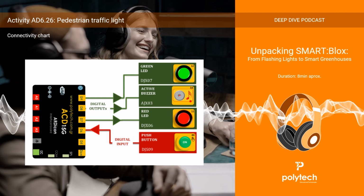The goal here is understanding digital read, checking the button state, and if-then logic, plus the digital write and delay we just saw. So if the button DJS09 on port D6 is on, then the green LED D9 and buzzer D8 turn on, the red LED D7 turns off, and it waits for 5 seconds. And if it's not pressed, that's the else part. Red LED on, green and buzzer off. Classic conditional control. You press the button, things change. Cause and effect.